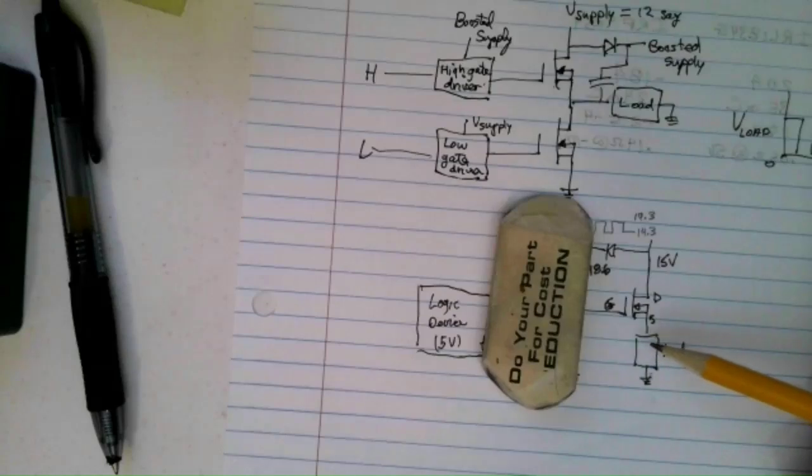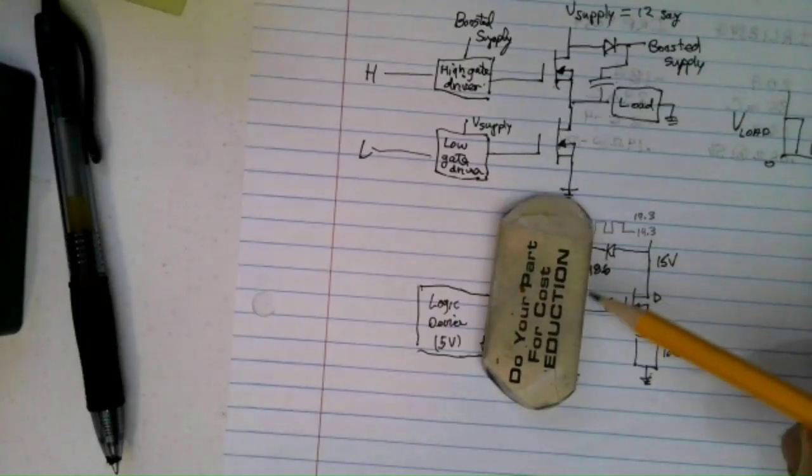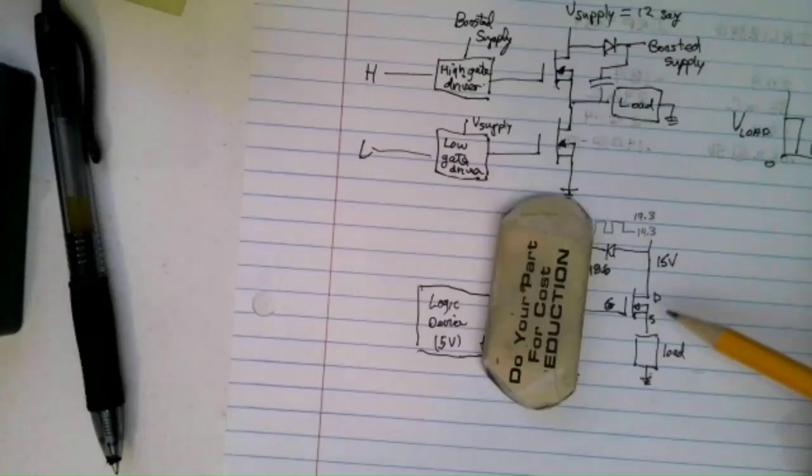And I would say that is unacceptable, in that if this was 15 volts you only have 11.5 across your load, and you have more than 50 watts power dissipation in the FET, and basically just bad performance. Now, why would you even want to try to do that, to use an NFET as a high side switch?